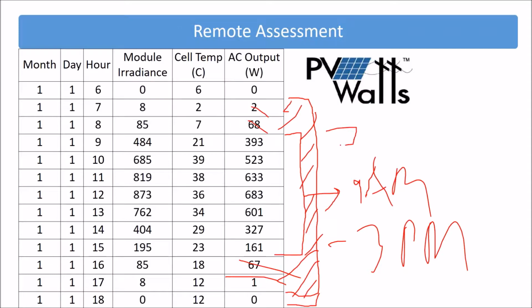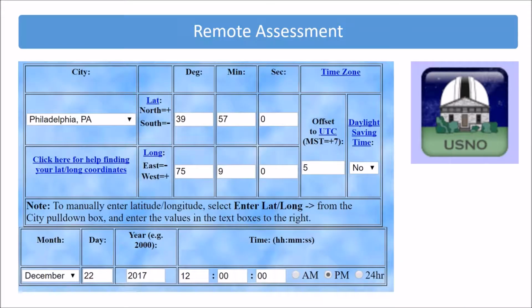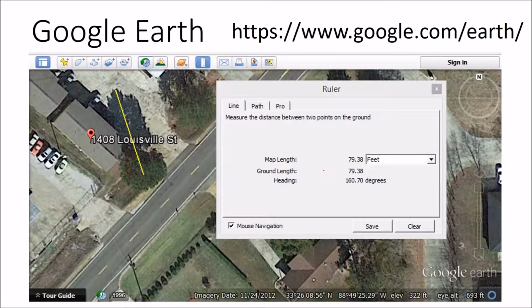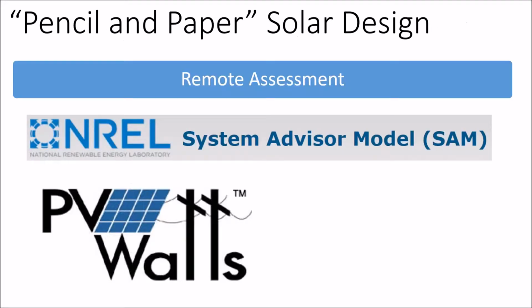I mean, you don't want shadows on your solar array at 9 a.m. And in a ground mount array, that might be row to row shadowing. And so you can start defining what is my PV Watts window, or what is my solar window based off PV Watts. And so then it comes back to, in order to figure out where the shadows go, I need to know where the sun is on winter solstice and summer solstice and spring equinox and fall equinox. And also to calculate the height of this tree, I need to know where the sun is on the date that the photo was taken, 2012 or so.